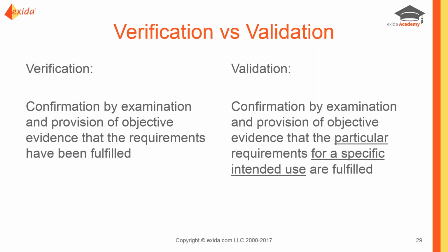It's important to note that validation ought to be one of the requirements for your pre-startup safety review, for going through that safety gate before introducing hazards to the process. And validation may well be one of the contract markers for turnover from the construction contract to the operating team. Again, your functional safety management plan is a very important place to have this, because it has not only safety implications, it has contractual implications as well.